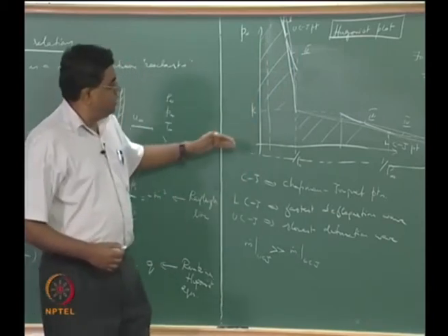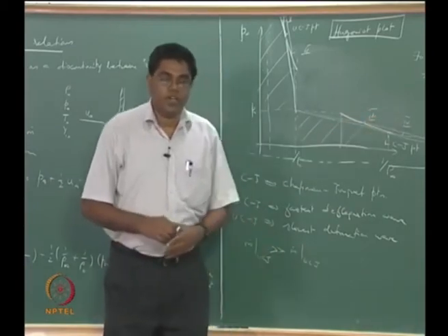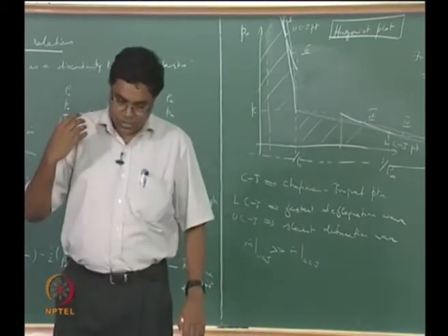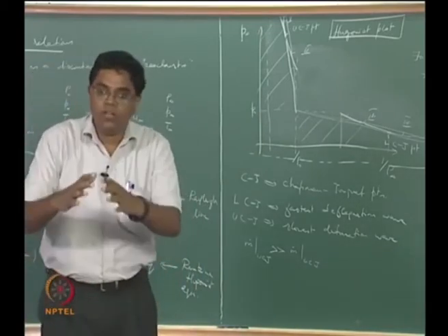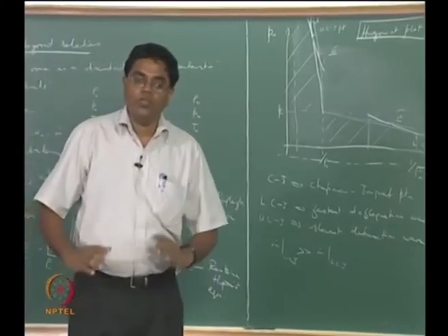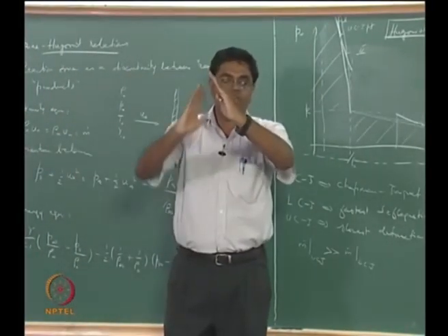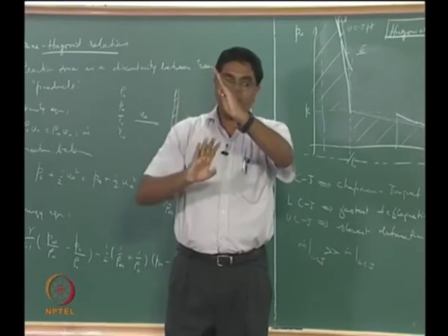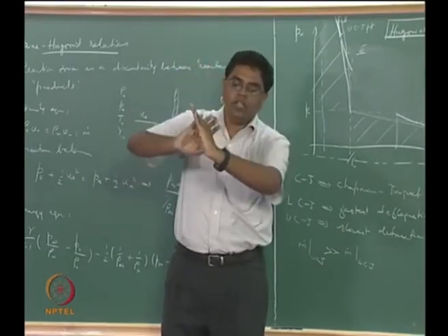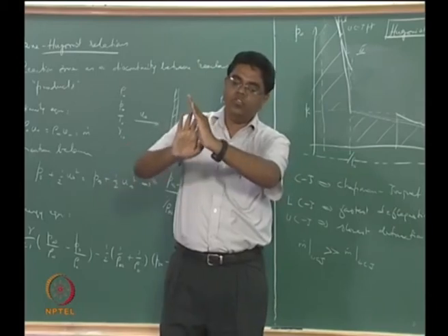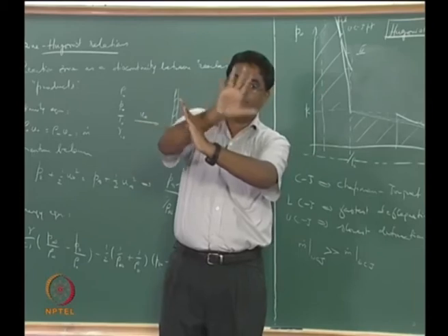When you are thinking about deflagration waves, this is actually more commonplace in terms of daily experience, like what happens in a Bunsen burner for example, right. So if you now have a Bunsen burner and then you have a cold reactant flow that is approaching the Bunsen burner, and then it goes through the flame, and the flame is like a conical flame, and the flow goes through this, it now expands and then kind of goes like that.